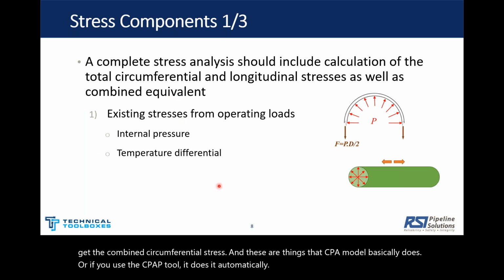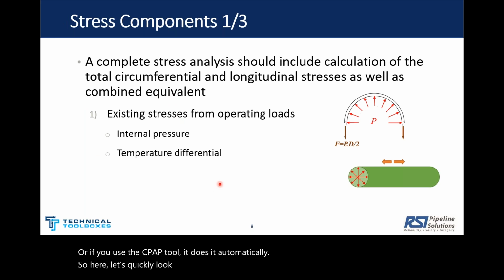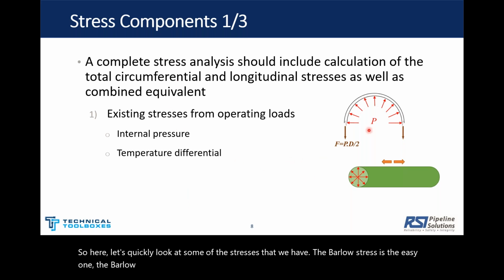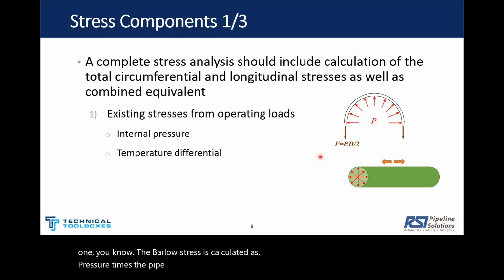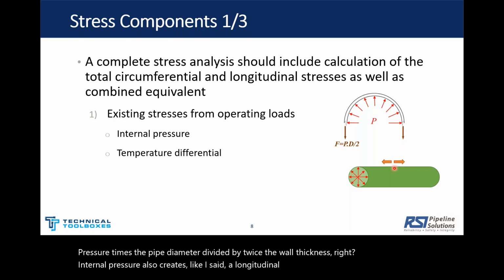So here, let's quickly look at some of the stresses that we have. The Barlow stress is the easy one. The Barlow stress is calculated as pressure times the pipe diameter divided by twice the wall thickness, right? Internal pressure also creates, like I said, a longitudinal stress when the pipe is buried.